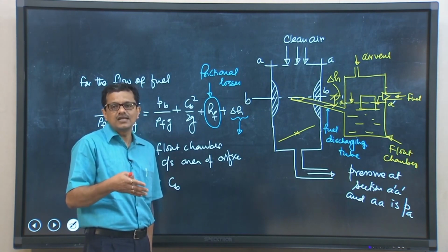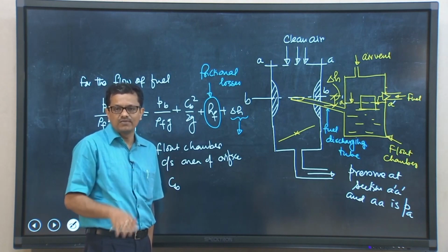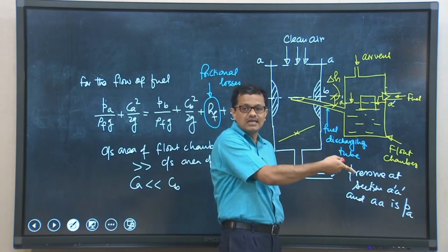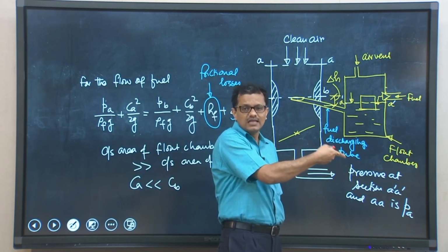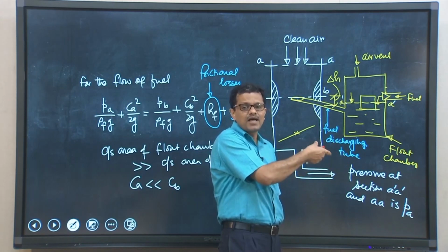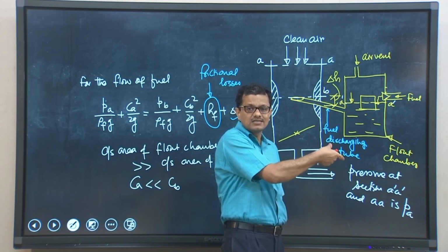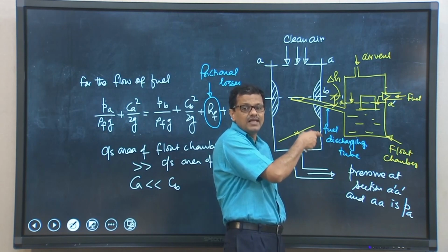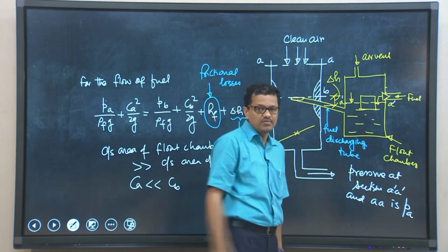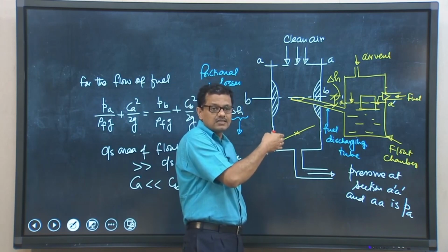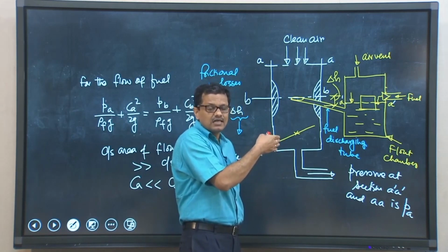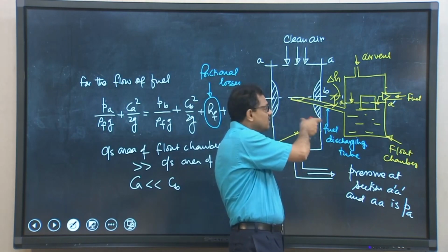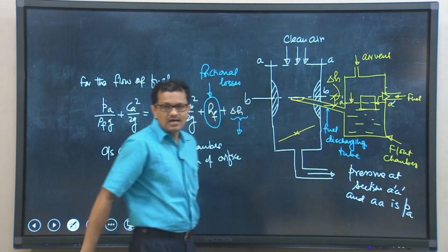Remaining 3 other strokes are the idle strokes, and we do not require to supply air fuel mixture. So, that means it is a kind of periodic supply of air fuel mixture to the cylinder during the operation of the engine, and that periodic supply to a single cylinder 4 stroke engine will bring unsteadiness in the flow of air. If that particular aspect induces unsteadiness in the flow of air, the flow of fuel also will be unsteady.